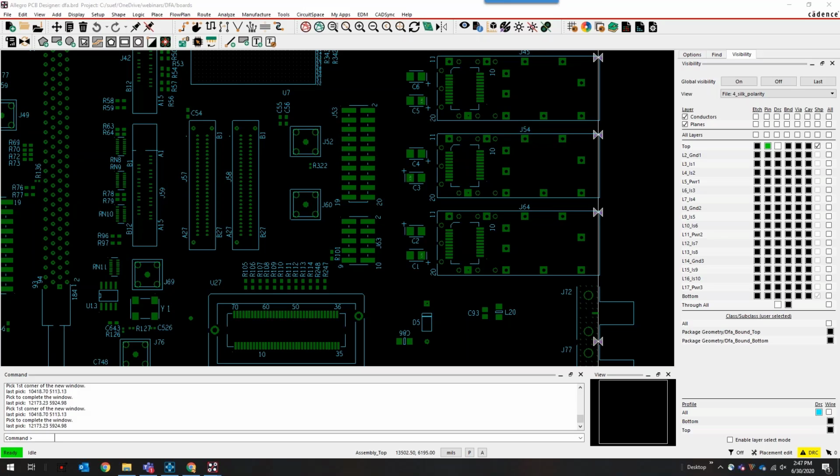The layer stack up is there. All the solder mask, all the paste layers are all there. They don't have to adjust any of that. So really, you want to start getting away from ever using Gerber data with your manufacturers. You can also ask for discounts because they do have to manipulate that, so your NRE could drop as well by giving them ODB++ or the IPC standard format.